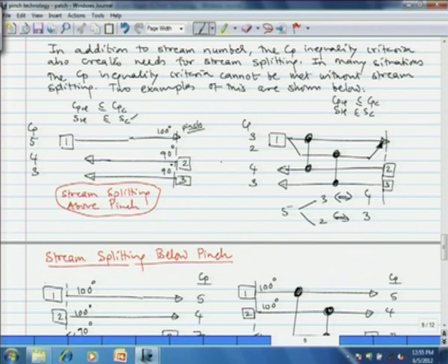The solution to this problem is that we split stream 1 into 2 parallel streams, and the Cp values of the split streams are 3 and 2. So, Cp value 5 is split into 2 branches with Cp 3 and 2, and now these 2 branches are matched with streams 2 and 3, because the first branch with Cp equal to 3 is matched with stream 2 with Cp equal to 4.